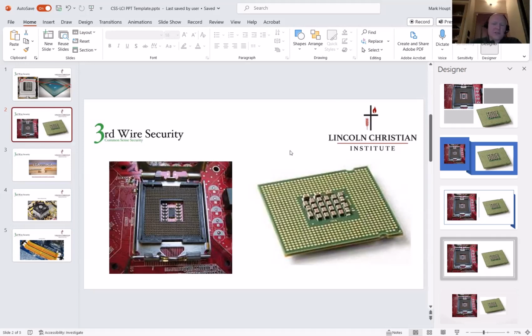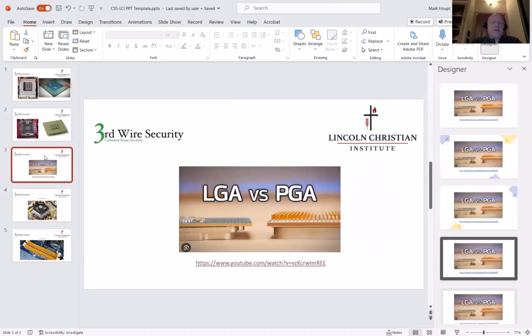Now on this particular chip, you can notice that there are little half circle indentations on the right hand side of that chip, and if you look closely at the socket, you will see the corresponding indentations. So again, unless you're forcing it and doing it wrong, you cannot put this chip onto the socket incorrectly. And again, once you lay the chip in there, make sure that you lock it in place to ensure that it works.